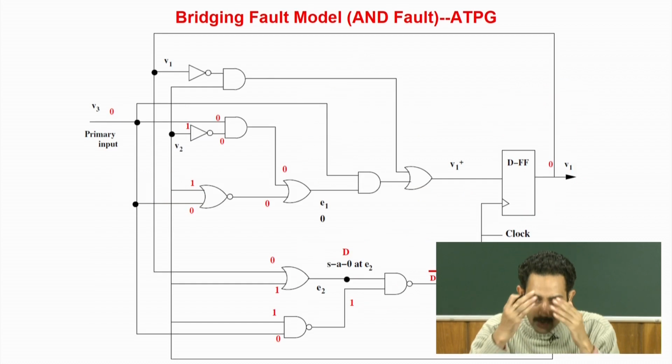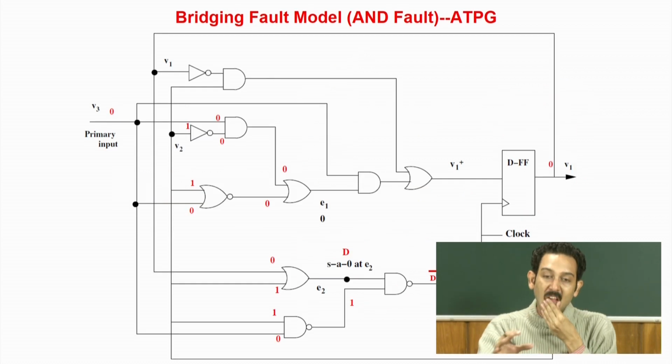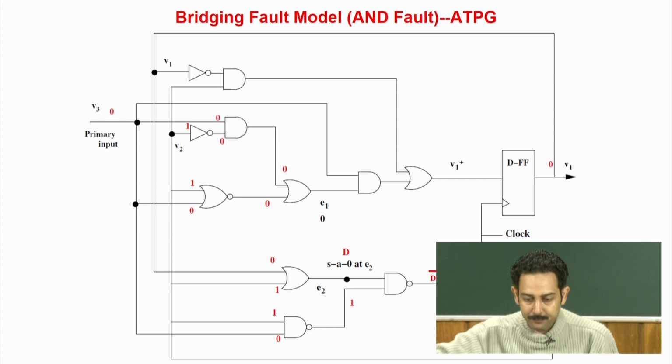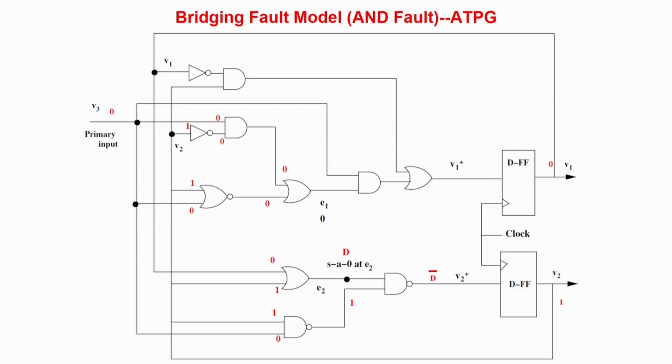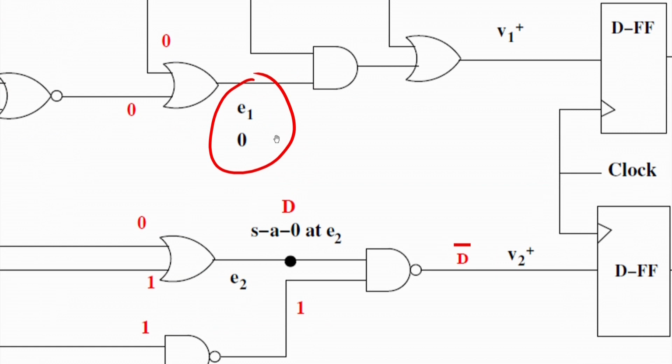Okay. So now let us look at the example we were discussing in a more colorful, animated and better manner. As I told you, we are taking the example where E1 has the value of 0, and let me zoom this part. So we take E1 equal to 0, and you have to find out whether E1 is dominating E2, that is, it should be 1, but actually it is making it 0. So you have to test a Stuck-at 0 fault over here.